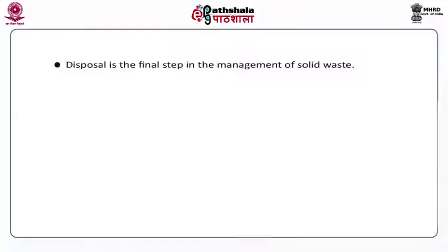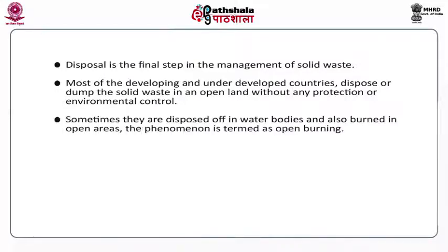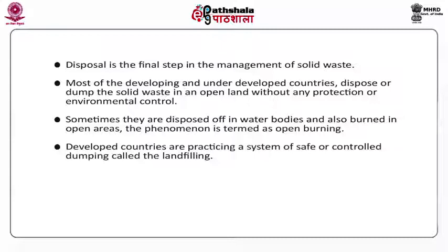Disposal is the final step in the management of solid waste. Most of the developing and underdeveloped countries dump their solid waste in open land without any protection or environmental control. They are disposed of into water bodies or just burnt in open areas, which is generally termed as open burning. The developed countries are practicing a system of safe or controlled dumping called landfilling.